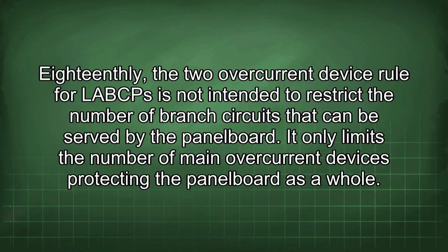18thly, the two overcurrent device rule for LABCPs is not intended to restrict the number of branch circuits that can be served by the panel board. It only limits the number of main overcurrent devices protecting the panel board as a whole.